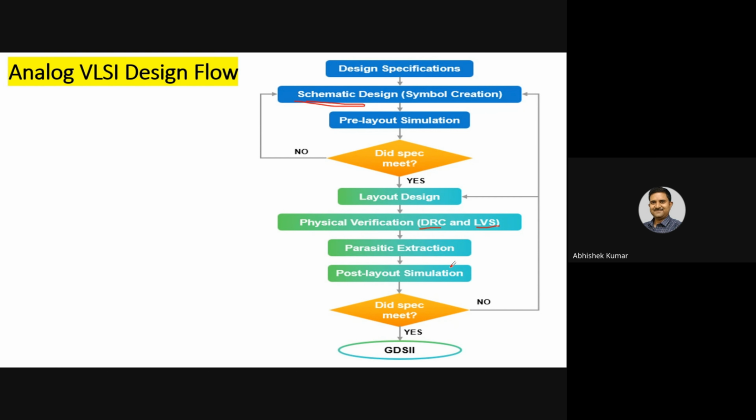That is your DRC. Now LVS comes in: it checks how the schematic has been designed and whether the layout is the same or not. If they are both the same, that's good. If not, then we have to redraw or reconstruct the circuit.